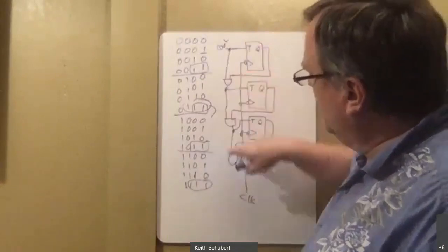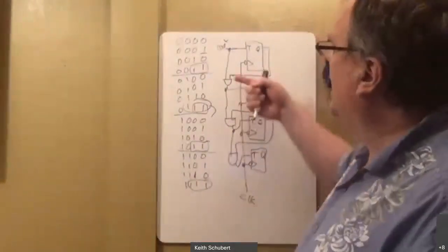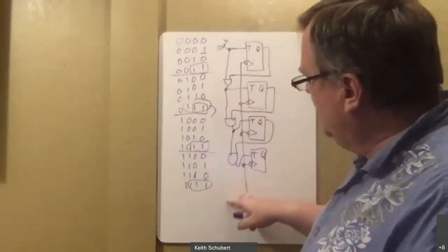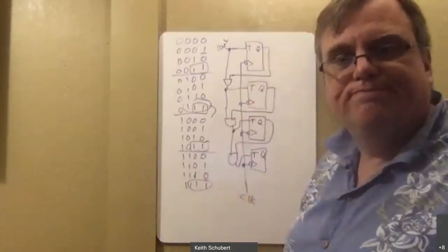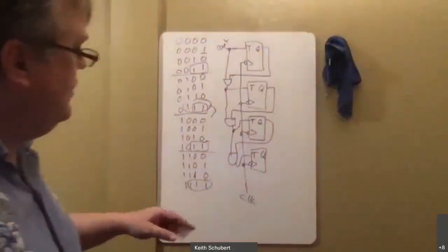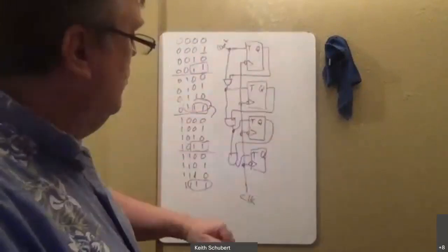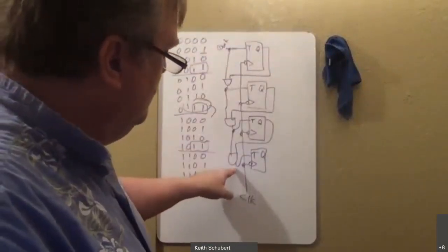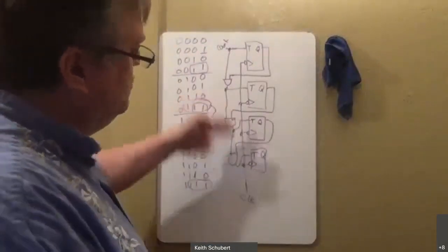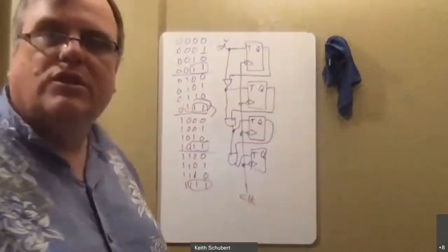So if the number of AND gates gets too large, one efficient way is doing block versions of these. I just take the number of these, and I cascade them like this. When it gets too slow, I do a single gate that takes all the previous ones. And that way I can get a quicker answer. Various speedups without necessarily having to have lots of different AND gates in between. But this design will work. Eventually it will get too slow on the latency to meet the clocking constraint. Then you have to go to wider gates where you smush a couple together. But essentially that is the design. Do we feel good with this?